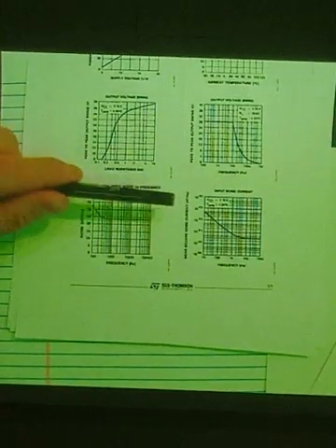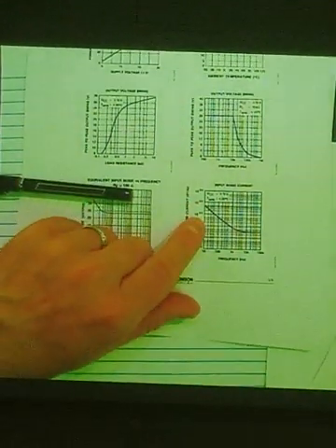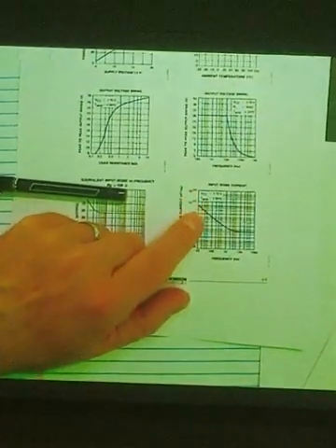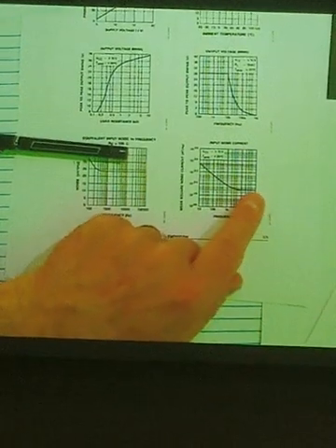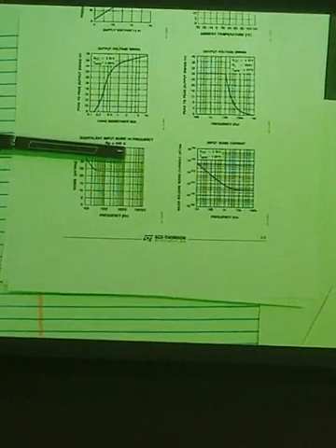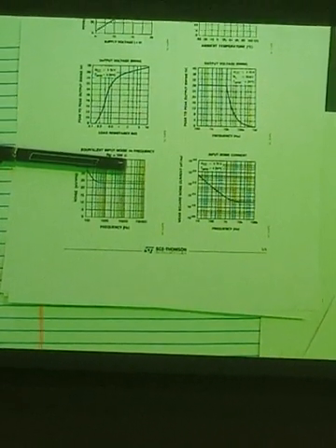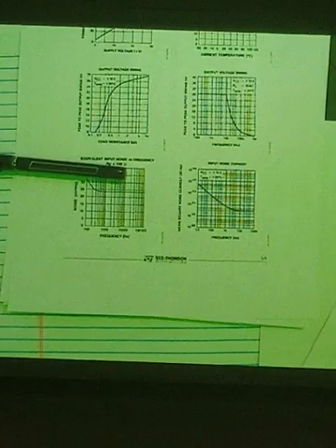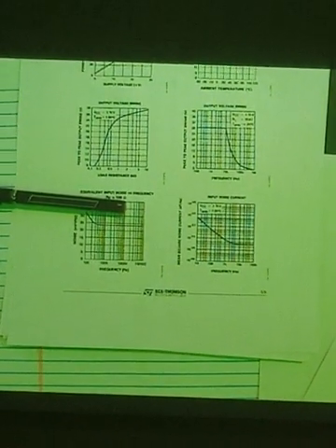In other words, work with amps per root hertz rather than amps squared per hertz, because look at the units here. You can read that, 10 to the minus 23. The floor here is about 10 to the minus 24 amps squared per hertz. Really small numbers. If we talked about that in terms of amps per root hertz, we take the square root of that, and at least it would be picoamps, 10 to the minus 12.